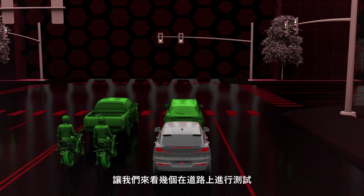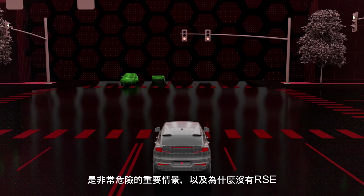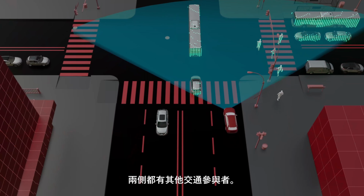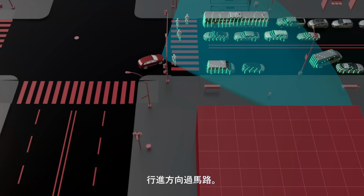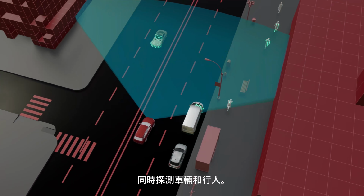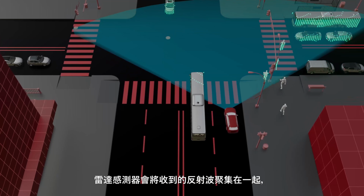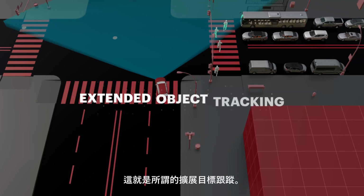Let's look at a few vital scenarios that are dangerous to test on the roadway and why those are hard to test in the lab without an RSE. Here, the host vehicle turns right on a street with traffic on both sides. Pedestrians and cyclists cross the street in the same direction of travel. The radar sensor must simultaneously detect vehicles and pedestrians as they cross the street. To accurately identify and follow the motion of an object, the radar sensor clusters reflections together. This is known as extended object tracking.